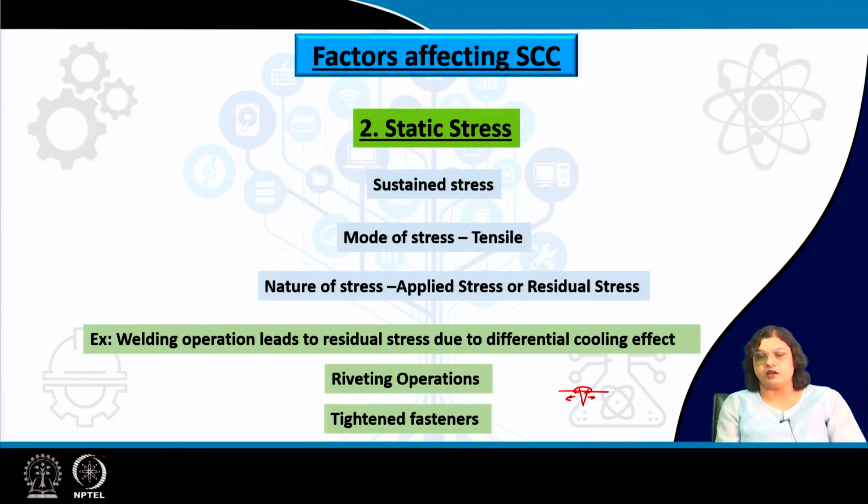Fasteners which are being tightened, of course, once again, particularly if we are doing this at a comparatively higher temperature, that can lead to some changes even in the microstructure. And as we can understand, during the tightening operation itself, some internal stresses will be stored, which will aggravate the situation, particularly in the presence of a corrosive atmosphere. The corrosion reaction will take place at a faster pace, and that will lead to earlier onset of stress corrosion cracking.